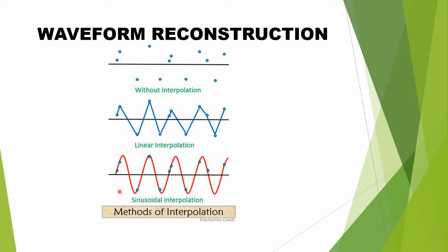The sampling technique gives rise to another problem when used in DSOs. The transients or glitches that exist in between the sample points can be missed out. This problem is solved by envelope mode oscilloscopes. The envelope mode oscilloscope employs special logic circuitry due to which the sample and digitizing circuitry run at high speed, the functioning of which is independent of the setting of display time.